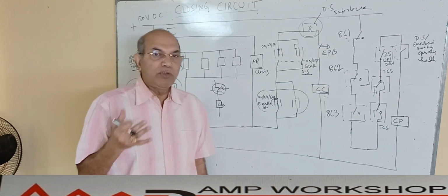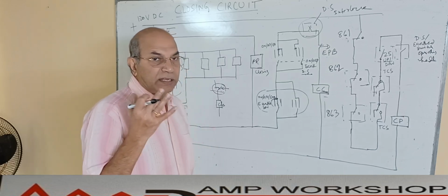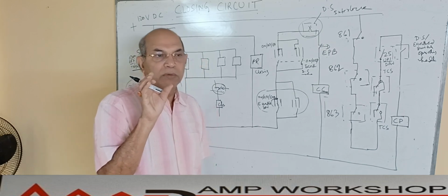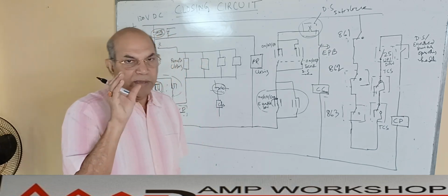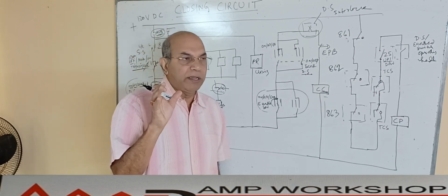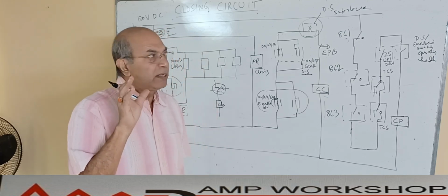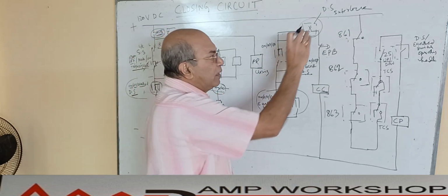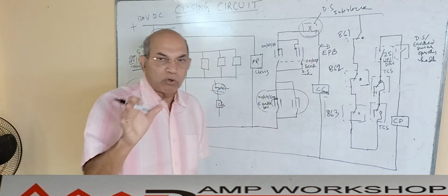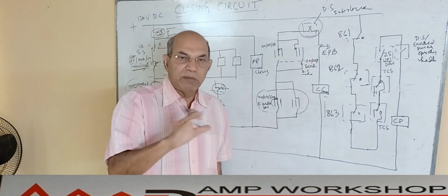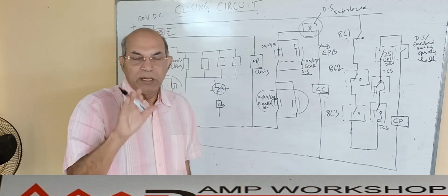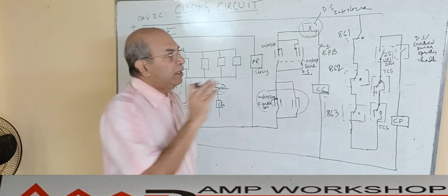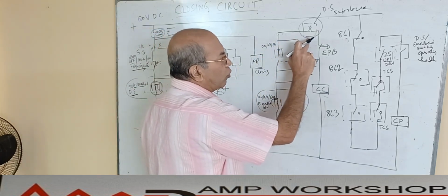That interlock we get from the disconnector switch. There is a small device which has a microprocessor, an intelligent device. That intelligent device can give a contact, and that contact is an NC contact. The NC contact means the system is okay. This spring charging system, closing circuit, tripping spring is fully energized, and you can close the breaker. That interlock is incorporated over here.